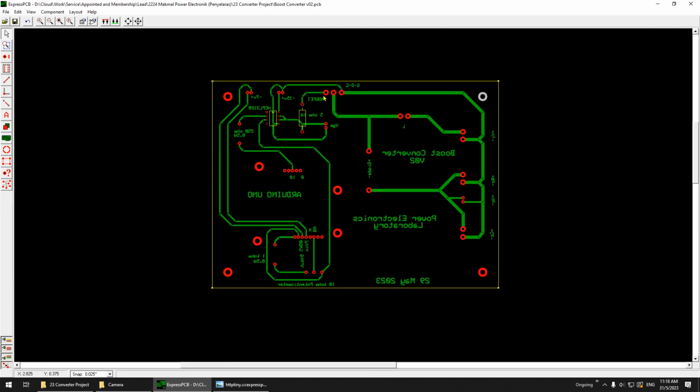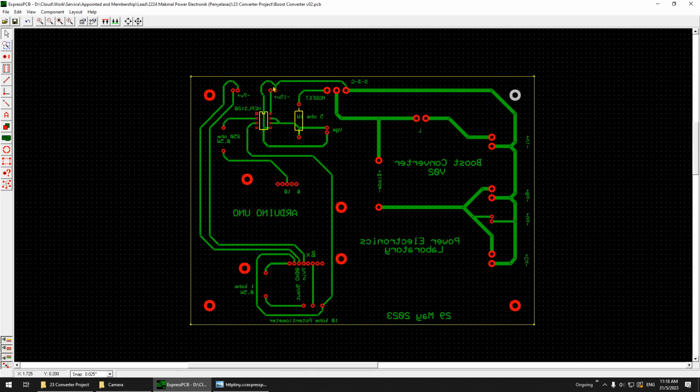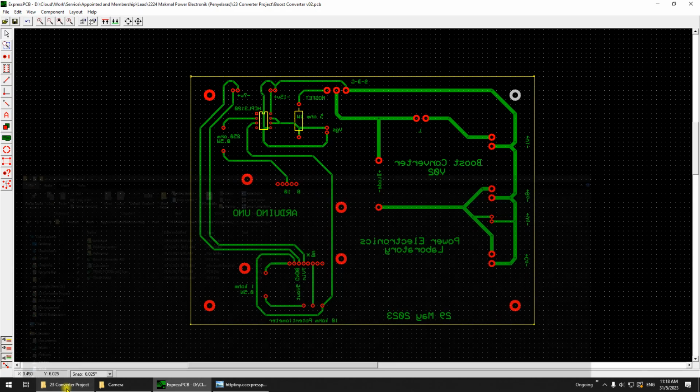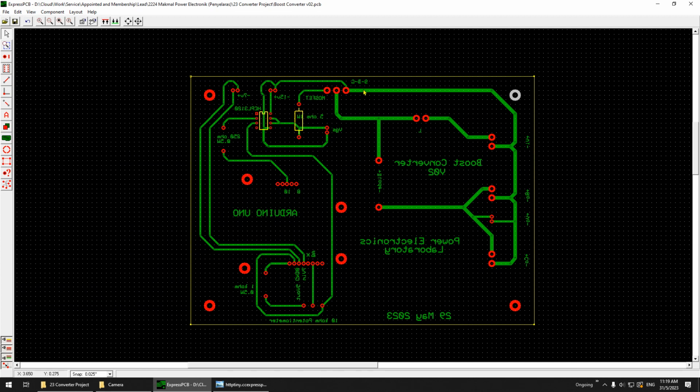Another thing is, if your board is too long, for this one it is 20 cm multiplied by 15, you should put another PCB stand. Why? Because if you have a lot of components here, or heavy components like an inductor, it will bend. Or maybe during the process it can also bend. So I suggest you put another one here, maybe at the middle. But this is not necessary if your components are low weight. For this one it is heavy, but in my design my inductor is put outside, so no need to worry for this. Or you can just put one at the middle for the PCB stand.